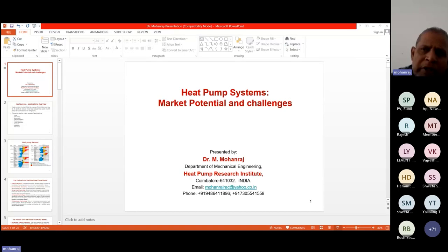But now the problem lies again with the phase-out of R134A with R1234yf. The reason is that R1234yf has been identified as having a short lifetime. It is an unsaturated hydrofluorocarbon that decomposes fast, and it creates more environmental impact immediately compared to R134A. So R134A will give a late impact, whereas this will give a sudden impact. That is not good for replacement, but it may be considered as an interim option.